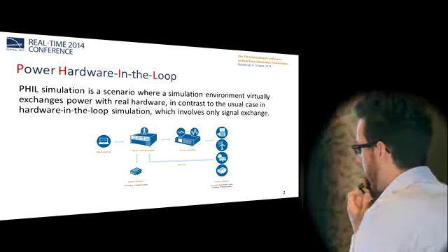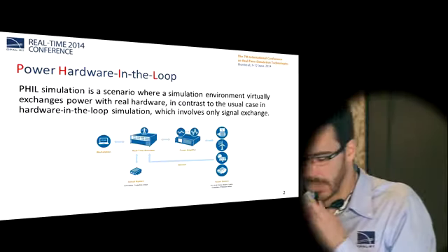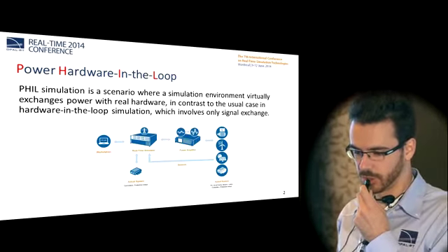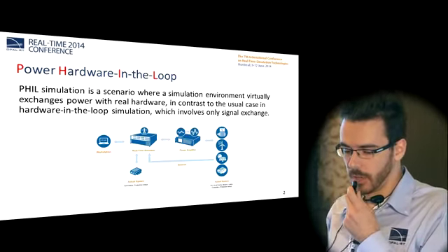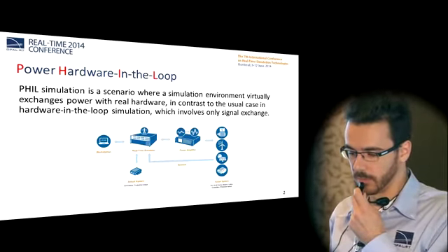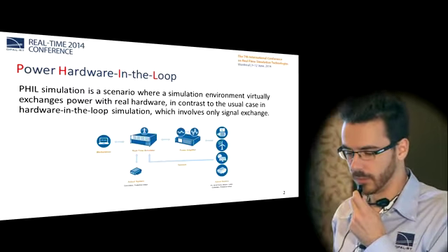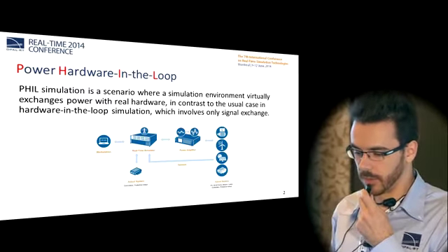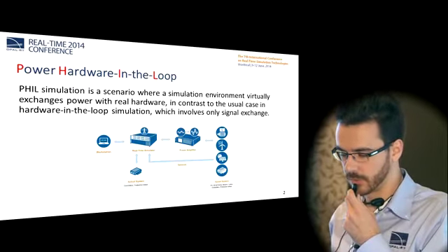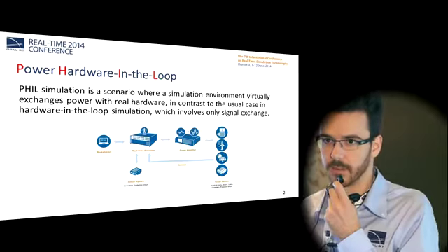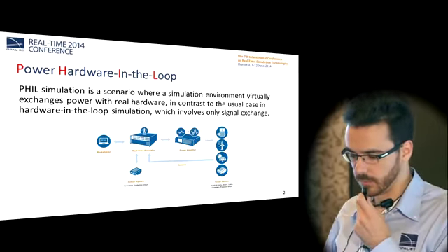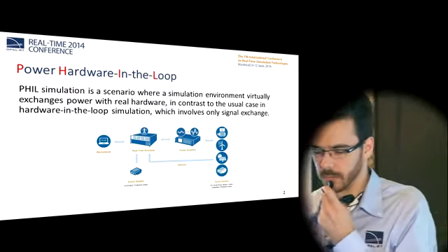Like we can see in the schematic, we have on the complete left the host workstation, which controls the simulation on the target computer. Then, from the target computer, you can control signals going through the amplifier to connect with real hardware. Afterwards, the results that are taken from the real hardware through sensors are re-injected back in the simulator, where the equipment results can be taken into account in the model.